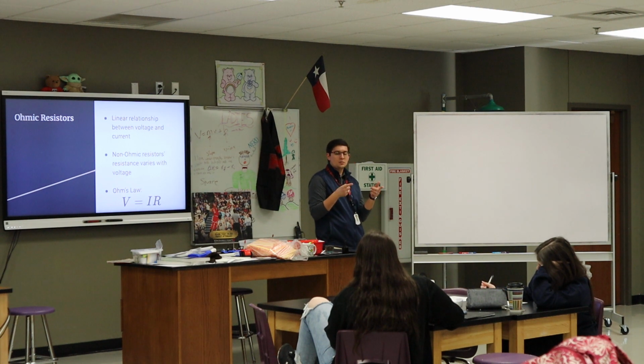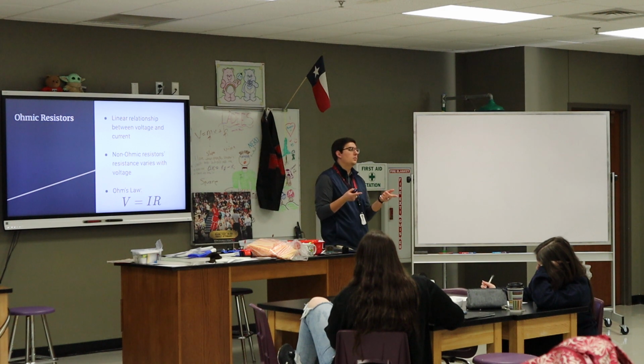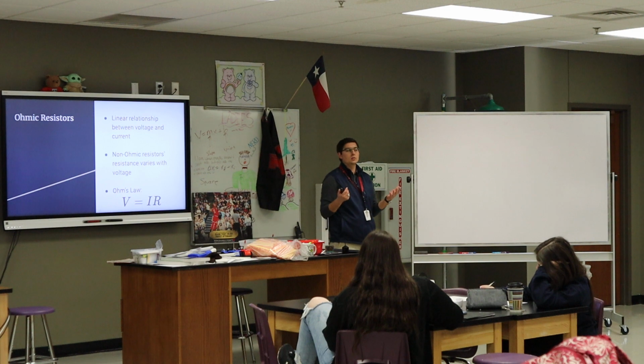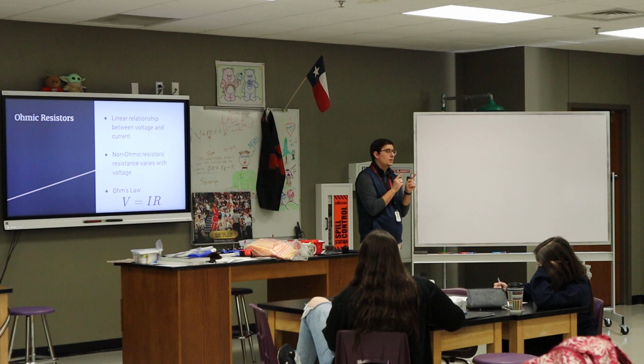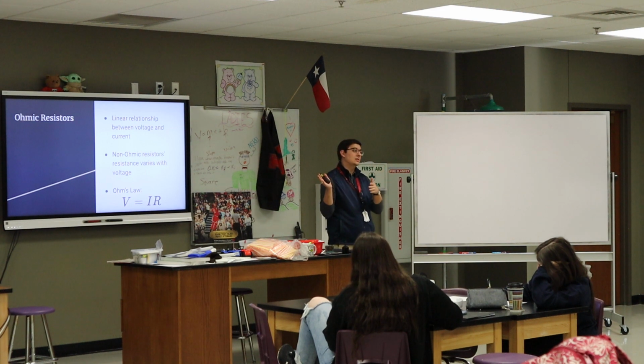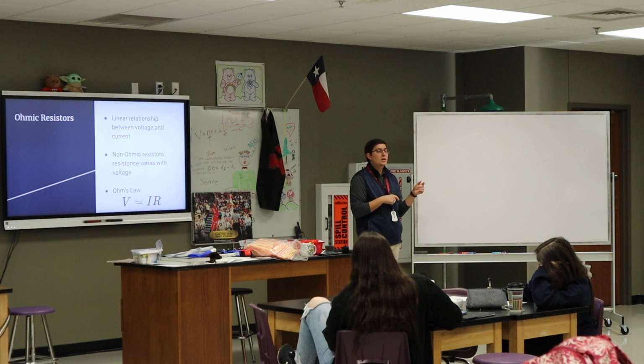In other words, if I double the voltage, I double the current. If I quadruple the voltage, I quadruple the current. However, most materials only have a small band of voltages within which they behave in an ohmic fashion. What really happens is you see these critical points where there's not enough voltage to get anything to move, and then on the higher end there's a voltage high enough that it starts to break down the material and current accelerates through it at a much higher rate.